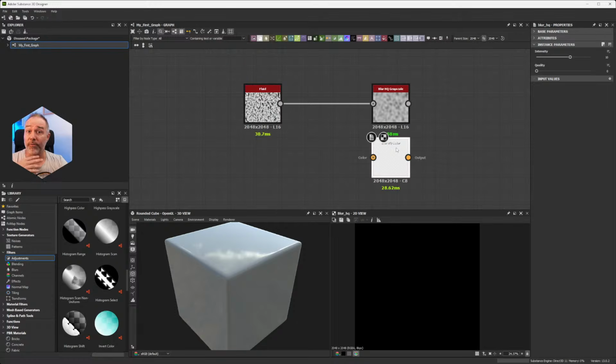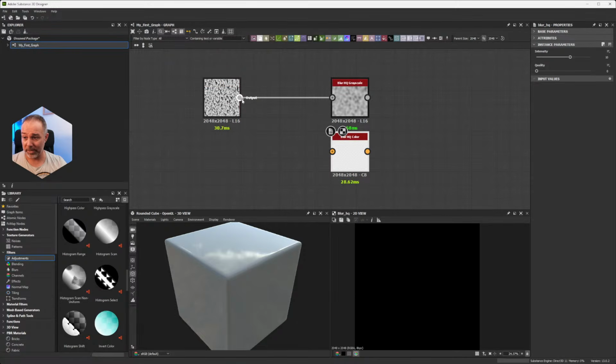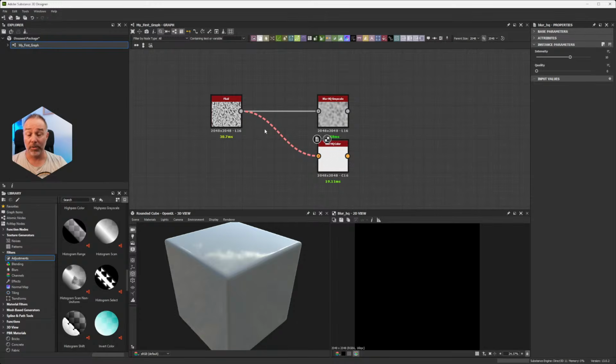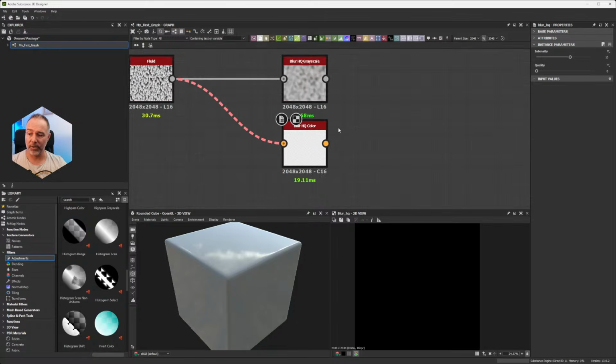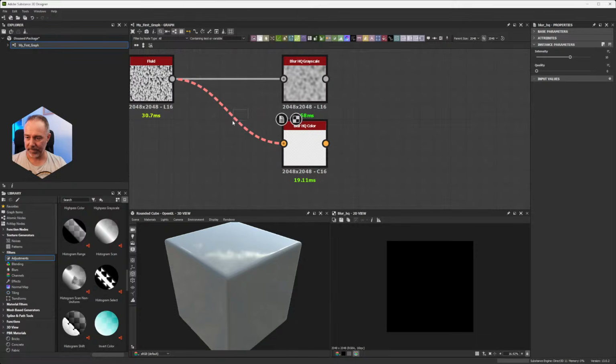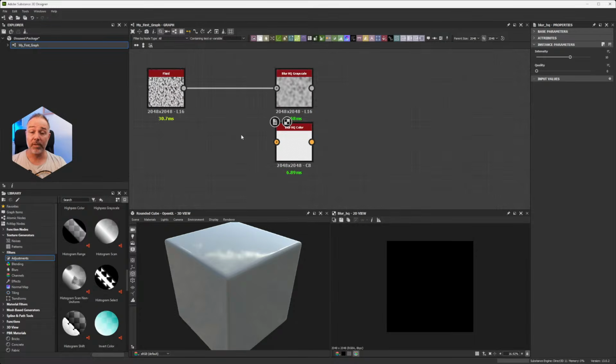But you have to retain that for color you would use it this way, but these are 4 channels, so they can be used the way you want. Sometimes people put different information in them. What is important in our case is that if I try to connect it, you have this red dotted link which says there is a problem. It will still work, but Substance 3D Designer will think, okay, there is nothing here, and nothing is 0, and 0 is black. So that's why the result here is black. When you don't plug something and it's expecting something, by default it will say it's 0.